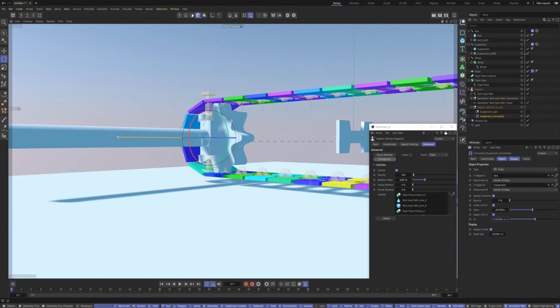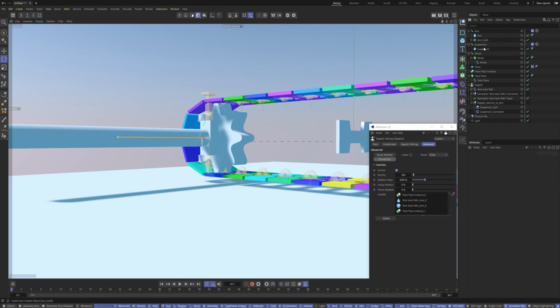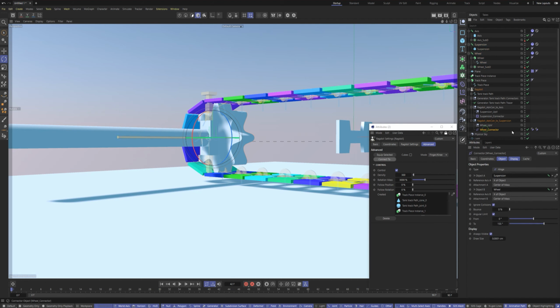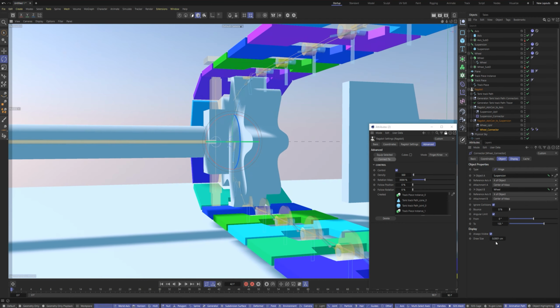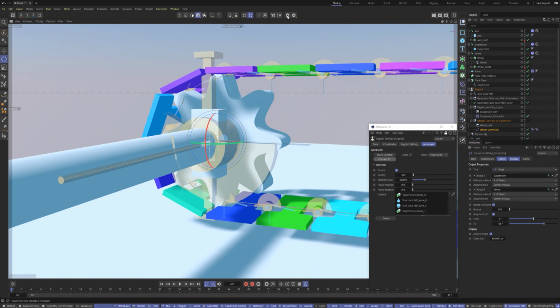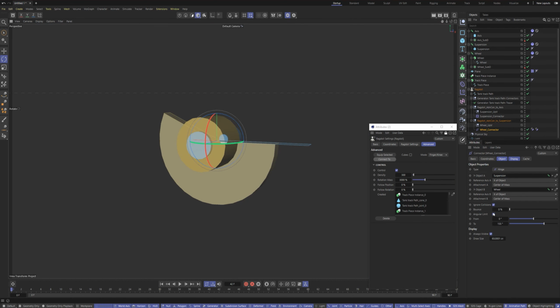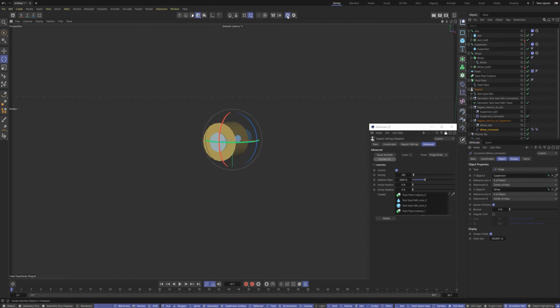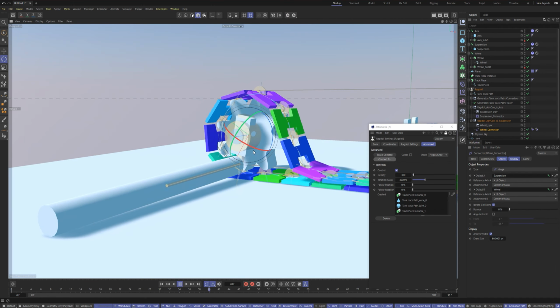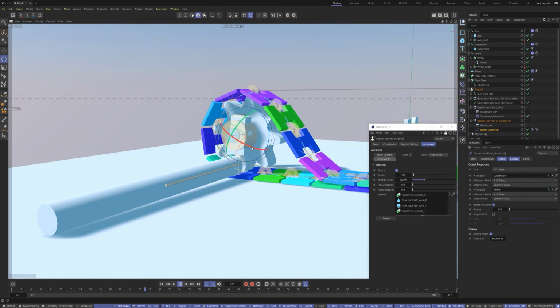As we can see, the drive gear is not currently attached to the suspension. Let's connect them too. Now choose the wheel joint and the suspension joint. This time we will connect them by the connector in the hinge mode. In the Ragdoll plugin, change the name of the mode to finger/knee and click Connect to. The Ragdoll plugin automatically created a correctly positioned connector in the desired hinge mode. All that remains is to disable the angular limit checkbox. We do not need any limits here. Now the gear is attached to the suspension, and the suspension is attached to the axis.